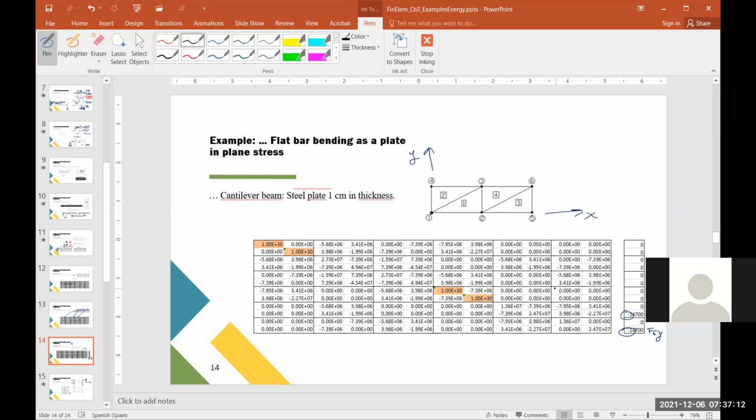When you do a partition, you place joints which help you to define elements. And then you go on with locating the forces and establishing boundary conditions, support conditions. So since you know what these boundary conditions are, what you try to do is you go back and try to establish a partition in such a way that you can apply the boundary conditions adequately. For example, if you have a joint where you know that this point receives a force, or you have a point where you know that there is some support, then you try to include there one joint in order to apply the boundary condition. Would you please repeat your question, please?